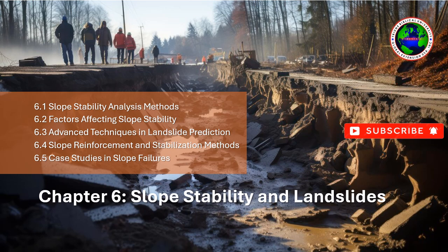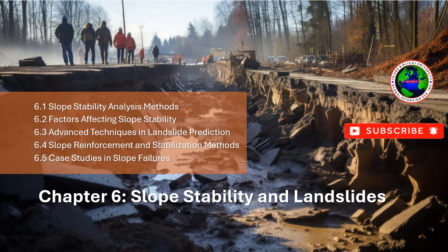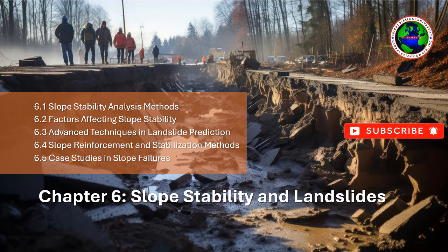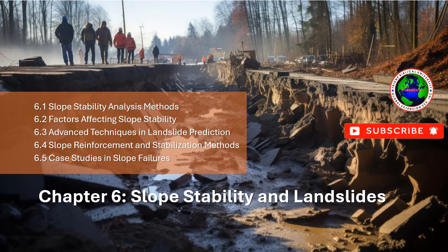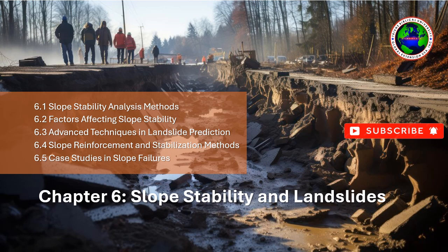FEM can model heterogeneous soils with varying material properties, making it suitable for more complex site conditions, such as layered soils or varying water tables. Stress-strain behavior. FEM can consider the nonlinear, stress-dependent behavior of soil, allowing for a more realistic representation of material behavior under loading conditions.